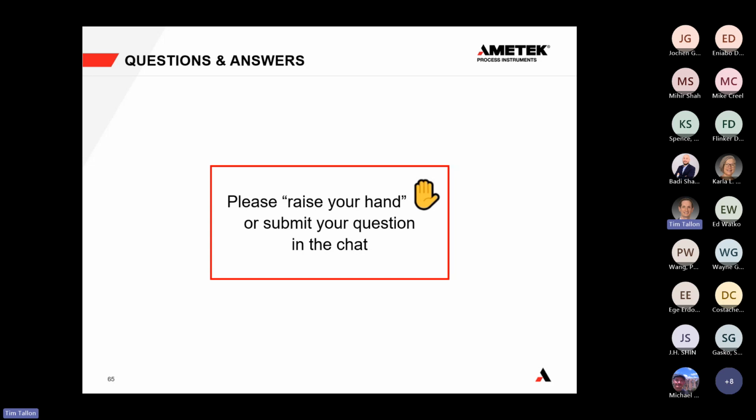And I'd also be mindful of installation so that there are no tubes, beams, debris or dust in the way that could interfere with the measurement. So that's also something I'd be cautious about: not only is it in a spot after the radiant section, but also that it's not interfering with the tube and there's no dead zone where it's not able to make a measurement. That's something to think about as well.